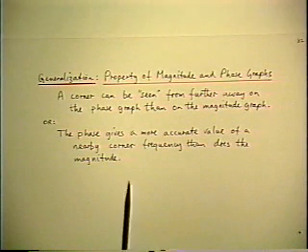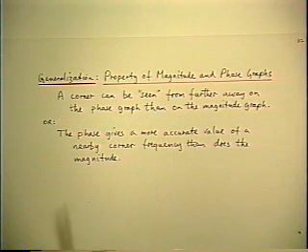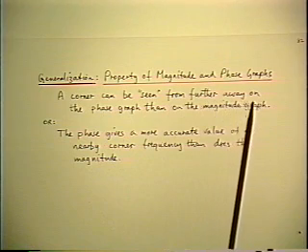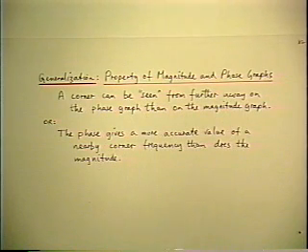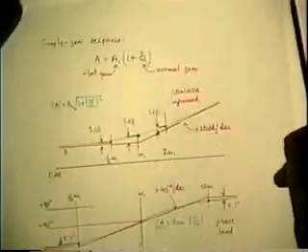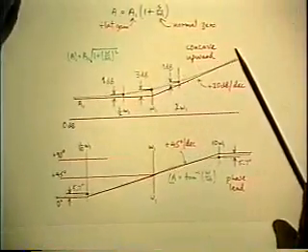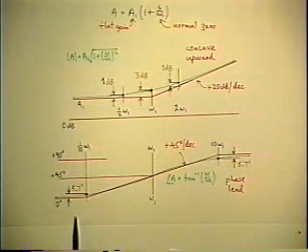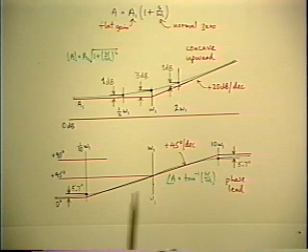Now you see why I made so much fuss about walking along the frequency axis and how far away from the corner the influence could be seen. The corner can be seen from further away on the phase graph than on the magnitude graph, because if you imagine yourself walking along the phase graph starting at 0 frequency, and you ask, when can you begin to see the corner?